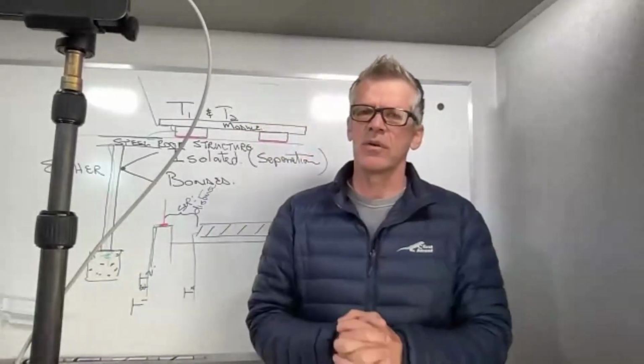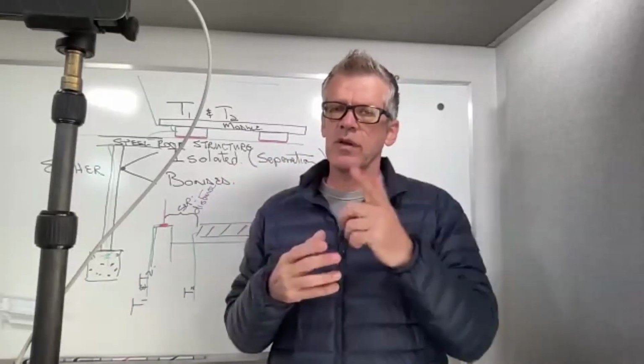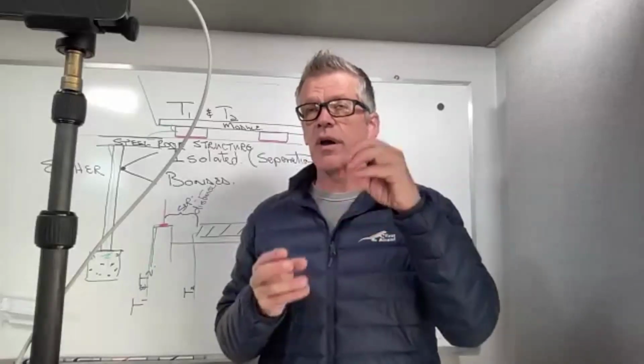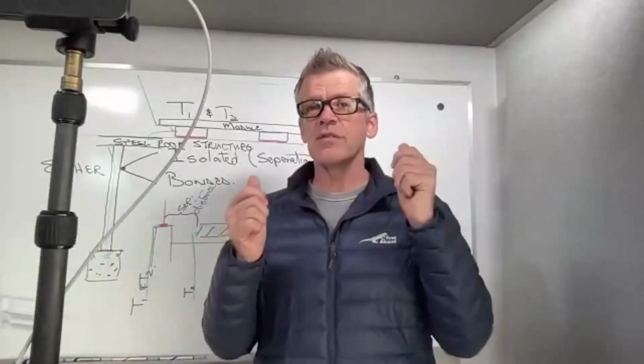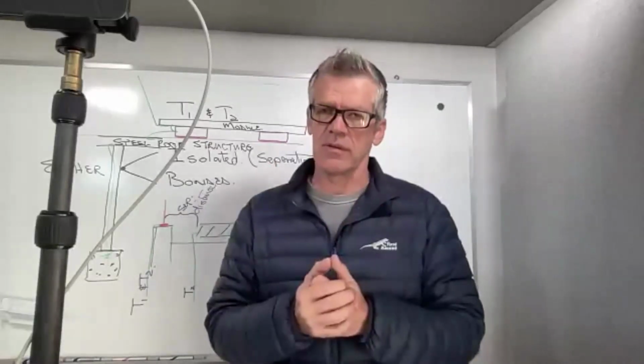Thanks for that, Kenneth. Moving on, Daniel says 50 millimeter square copper or aluminium, considering the current rating. Yeah, Daniel, yes and no. So the only time that you would use the 50 mil would be when you'd expect direct lightning. And for the 50 mil, you are actually using 50 mil for its mechanical strength and not for its electrical conductivity.